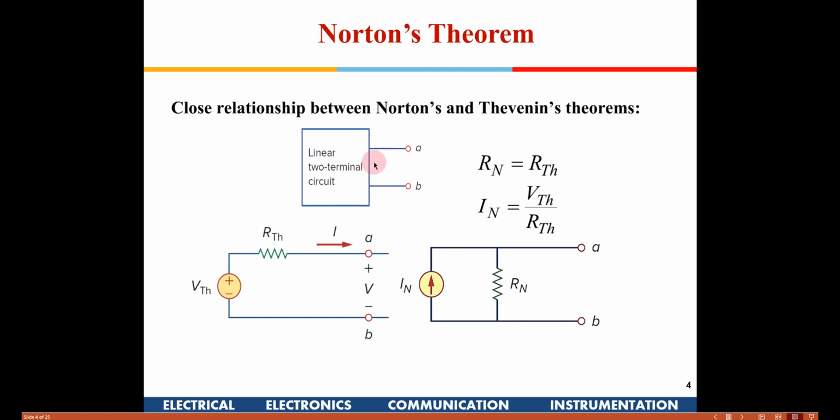Before we take an example, we need to understand that there is a close relation between Norton's and Thevenin's theorems. If there is a circuit, we can represent it by Thevenin's equivalent, which is a Thevenin voltage in series with a Thevenin resistance.